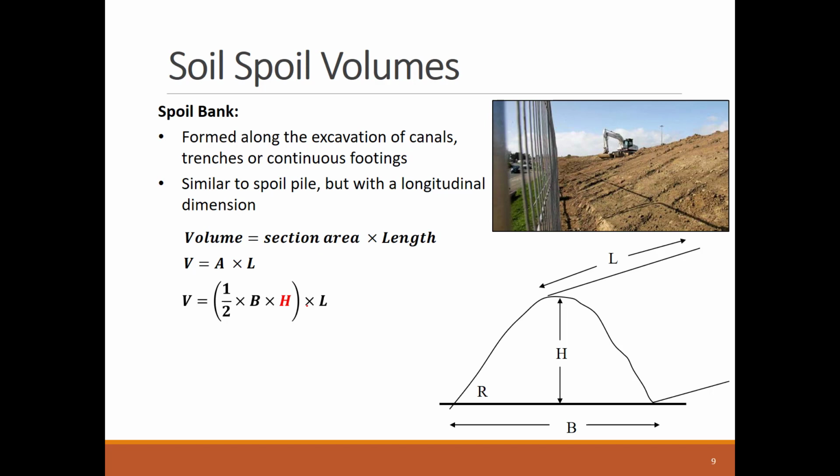The angle of repose relates the h and b variables, so we can adjust the volume calculation formula to make it a formula to calculate the pile bank width b based on the loose volume of the excavated soil and the excavation length and the angle of repose.